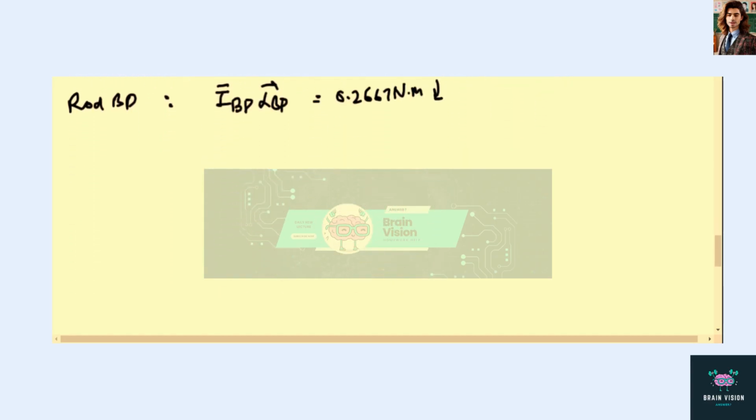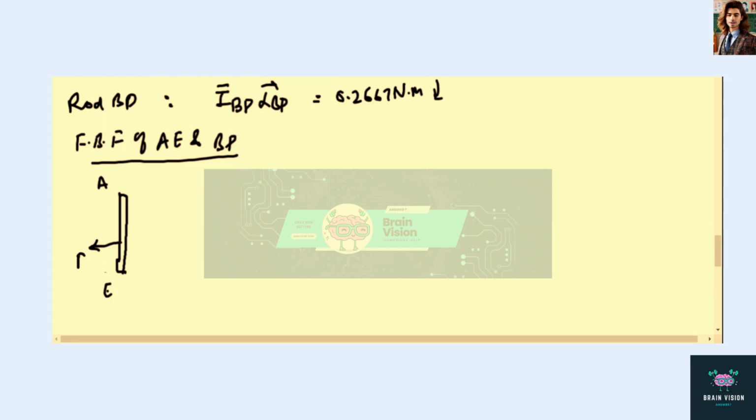Now we have to draw the free body diagram of AE rod and BP rod. First we will draw AE rod. This is A point, this is E point, this is P. Here reactions at A are AX and AY.